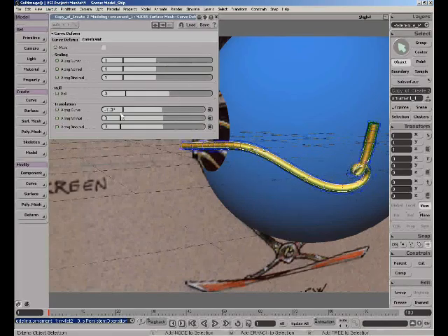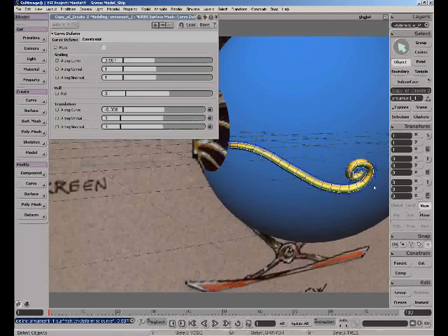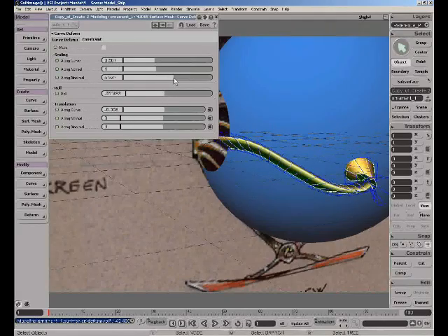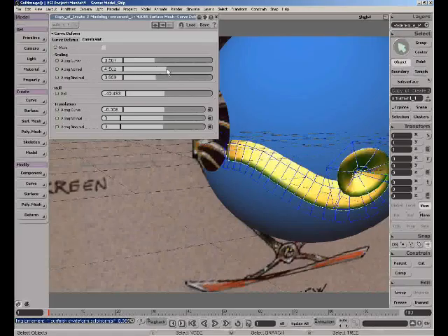I can move this back and forth like so, and you can see it scales and translates along that curve. And so now what I'm going to do is just go ahead and use the scaling and the translation to position that exactly on the surface of that ship, of that hull. And you can see we also have some tools here to roll that. If we want to rotate this, we can extrude this out like so.